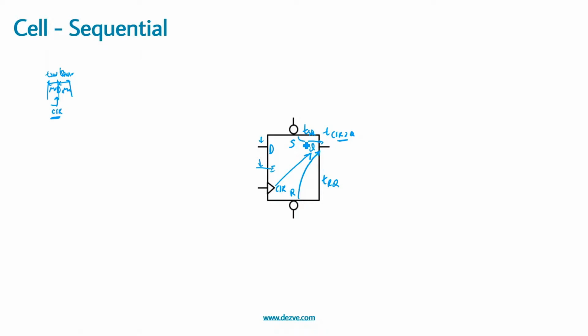Now when the asynchronous pins get asserted, after a certain amount of delay they can change the output pin Q. But when the asynchronous pins get deasserted, the deassertion can happen quite close to the clock, correct? Once the deassertion of the asynchronous pin occurs, the clock has to take over and continue the synchronous behavior. In that case, if these pins are changing very close to the clock edge, there could be a violation again on the output. These are called recovery and removal violations.